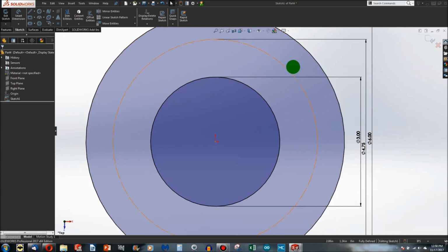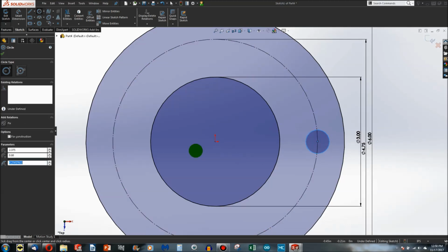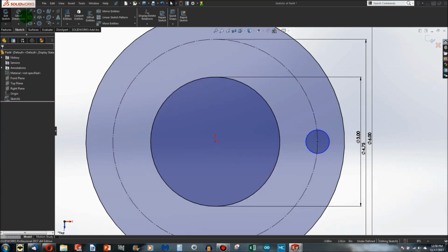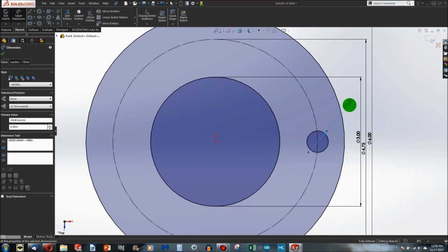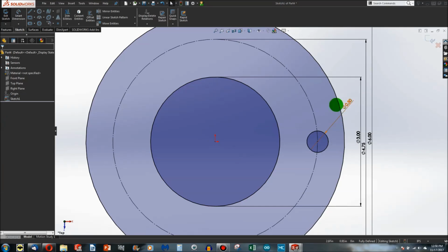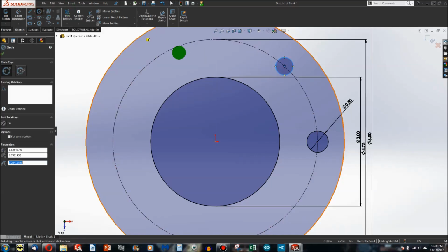Just like those construction lines that we've been working with, any construction geometry is for reference only. And so I can reference the location of all the bolt holes. The first one, I can snap it right to that point on the circle that is perfectly horizontal to the origin. I'll go ahead and make that hole 1/2 inch. I'll make 6 more holes.